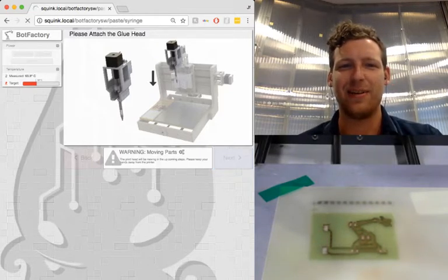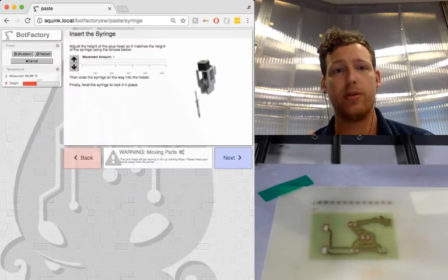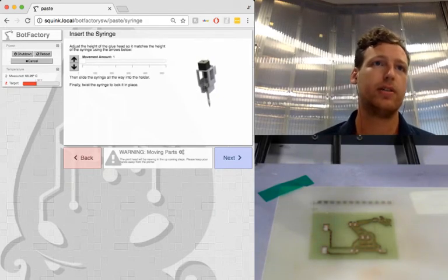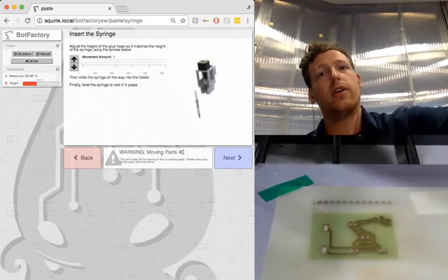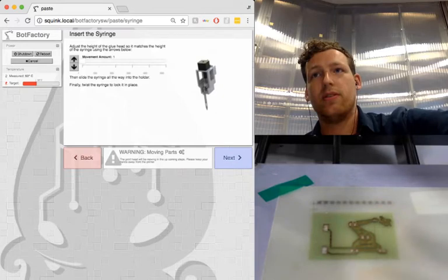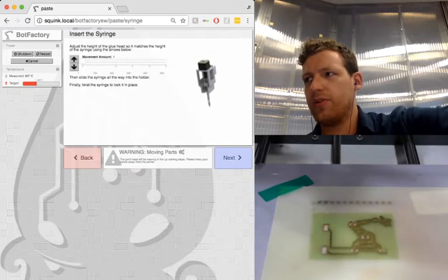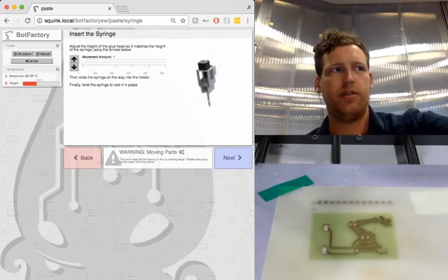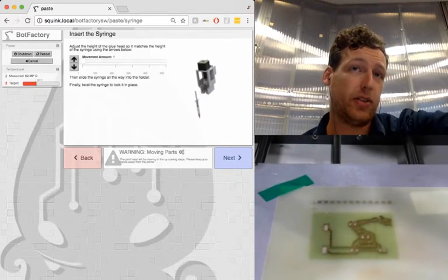Okay, so going to the next step, I attach the head. Oh, by the way, this is kind of critical that you actually put the head on at this point. You don't swap out heads at different points, because the drivers that drive the motor here are sensitive to changes in voltage. And if the motor is operational and you plug it in, the change in voltage will cause the driver in the back to switch off. There's basically a little tiny breaker on there.